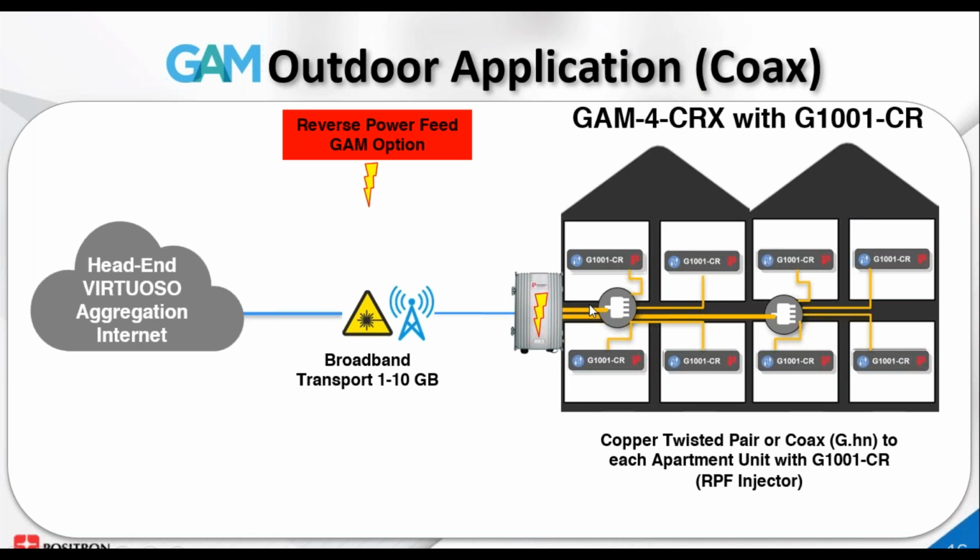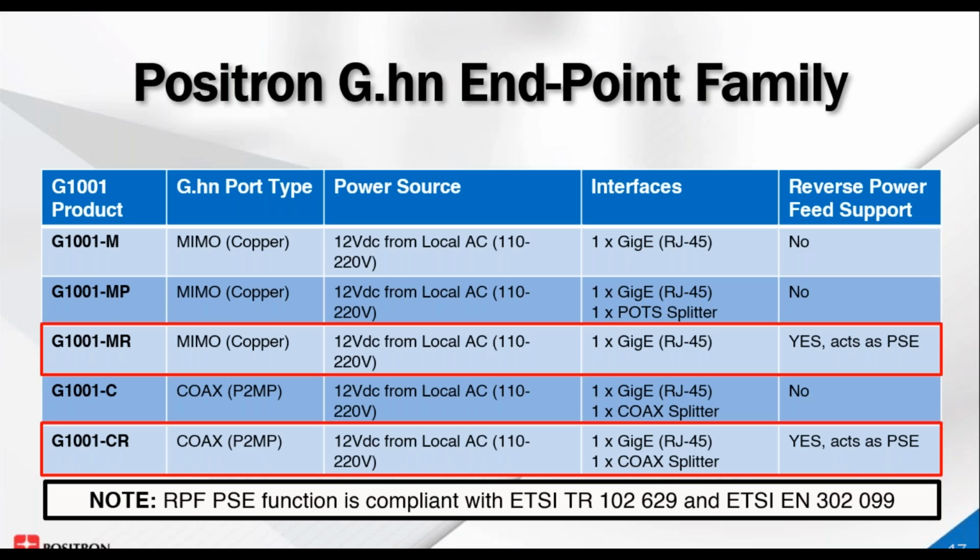That gives you a very low investment, much less than what the DOCSIS guys have to install and operate. No amplifiers. G.hn does not need amplifiers to achieve gigabit speeds at 2600 feet of RG6. So very easy, very cost effective to install, and very little maintenance.